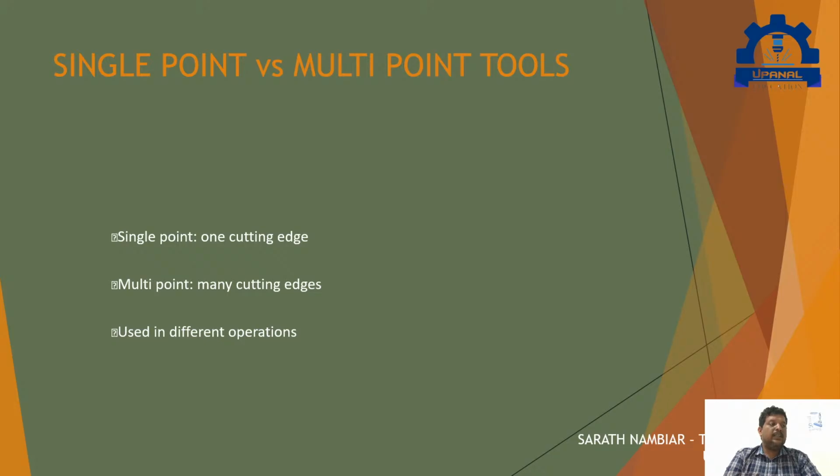Cutting edge is known as a single point cutting tool, whereas we have multi-point cutting tools where we have multiple ends, multiple edges, and these edges will be very useful for removing more material. Drills, end mills, reamers, all these things have multiple ending tools, multi-point tools, multiple tips. Say like 3 flute, 2 flute, 4 flute, 1. These things are called multi-point cutting tools, and we'll come to some tools just now.